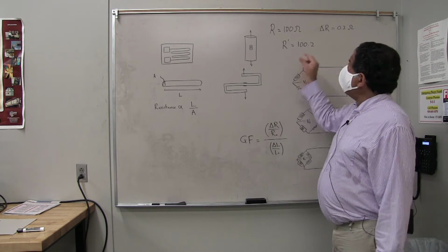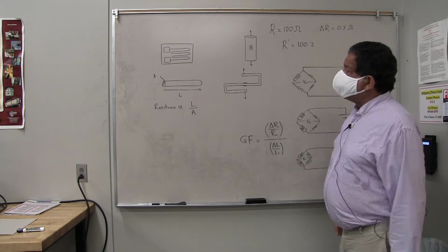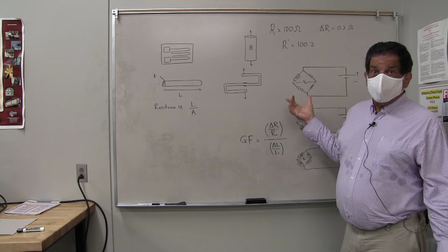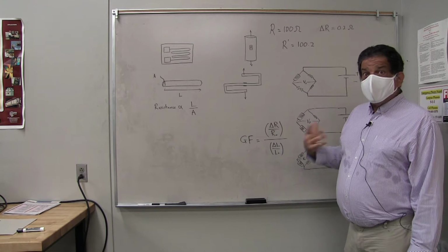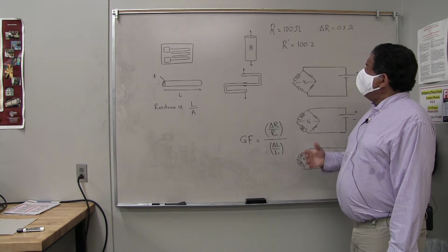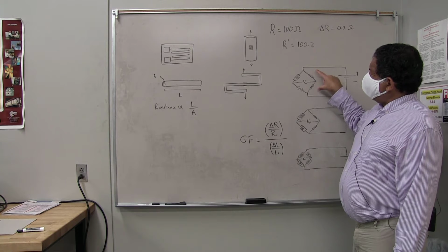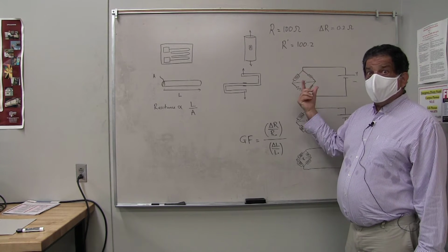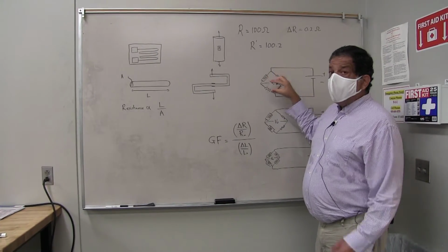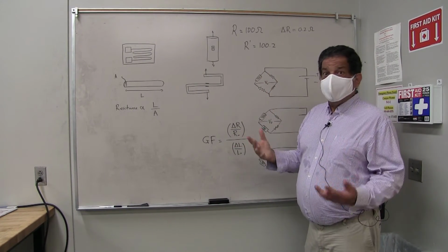The way that you can magnify this difference electrically is by using something called a Wheatstone Bridge. And this is implemented in all of the strain gauge readouts that we use in this lab. And essentially what a Wheatstone Bridge is that you have this diamond-shaped arrangement of 4 resistances, all of which are supposed to be nominally the same.